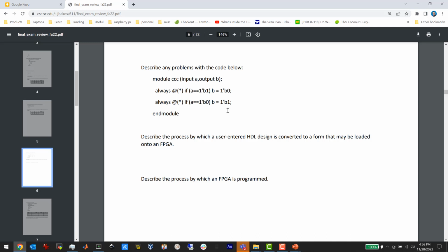The reason those steps are differentiated is because converting from Verilog to a netlist is very different from then taking that netlist and deciding what slots on the FPGA to put each of the nodes in that graph. That's a crazy NP-complete optimization problem where you've got these logical gates and then you've got physical gates, and I've got to pick logical gates and put them onto physical gates and then connect them through the interconnect fabric.